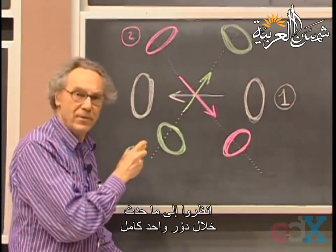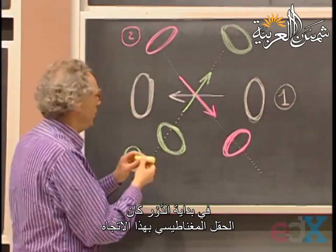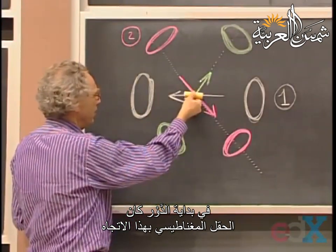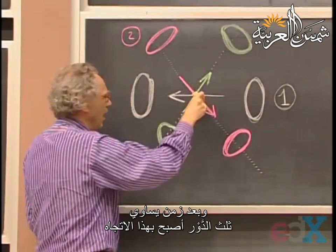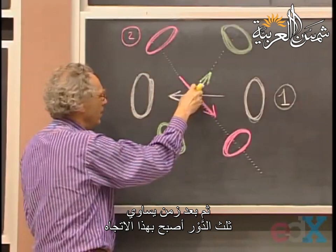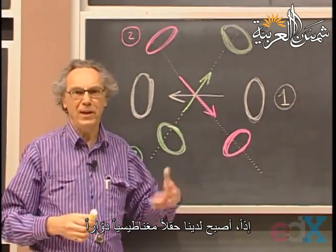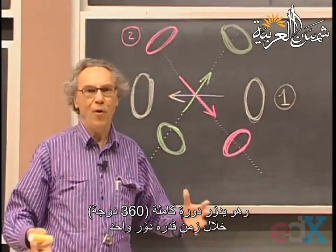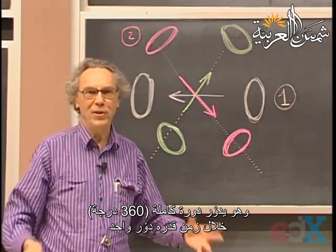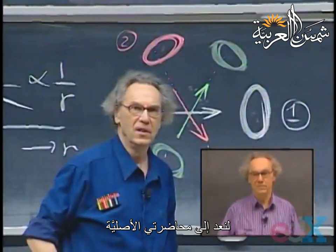And look now what has happened. In one complete period, the magnetic field started out like this. 1/3 of a period later it was like this. And 1/3 of a period later it was like this. So what we have created is now a rotating magnetic field. And it rotates in one period, all the way around, 360 degrees. Okay, let's now go back to my original lecture.